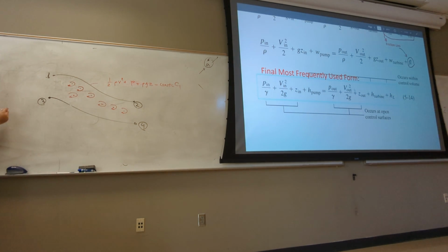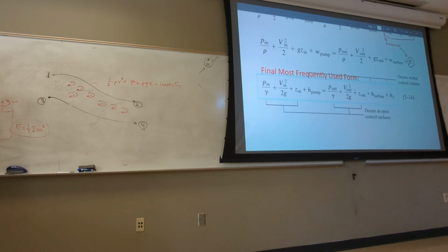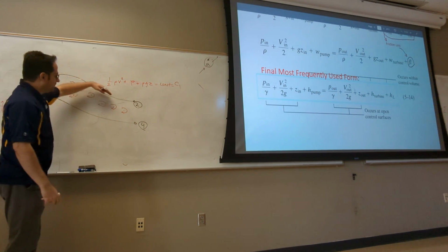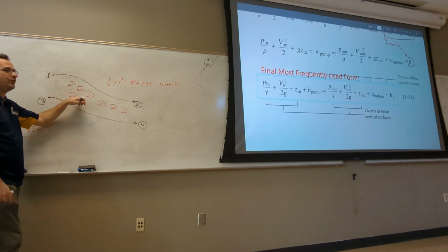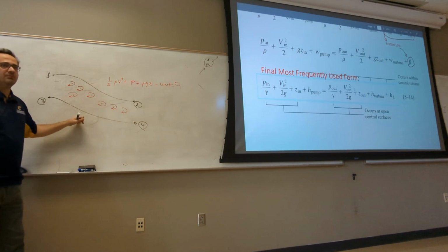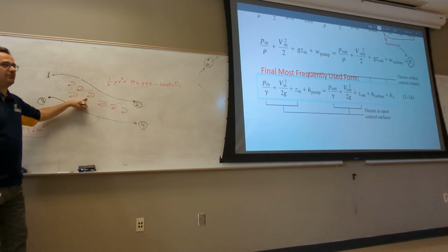You had it in dynamics, if you had an object like that, and this object was rotating with angular velocity omega, right? What was the energy of that? The kinetic energy was 1/2 of I omega squared. You had this in dynamics. Now imagine, look at it from the top, each one of these particles on the cylinder like that. So the moment you go from this streamline to the next one, if the flow is rotational, this constant will change, C1 and C2. But if the flow is irrotational, what happens?